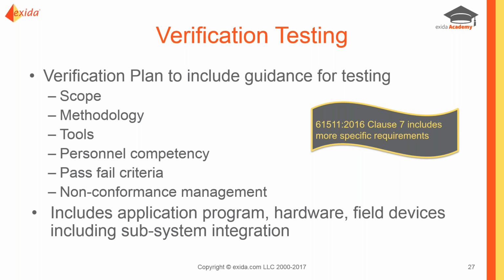There's a testing approach to the verification as well. A lot of what has been done up to the implementation phase has been theoretical verification against the calculations, against the data, against all the supporting input information. But it's very important to do this testing activity as you're going into the implementation phase, to look at the various criteria, not only of the hardware and devices, the logic solver. There will be a factory acceptance test. There ought to be a site acceptance test and a site integration test that goes with that.